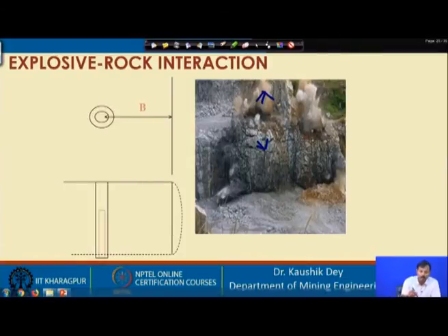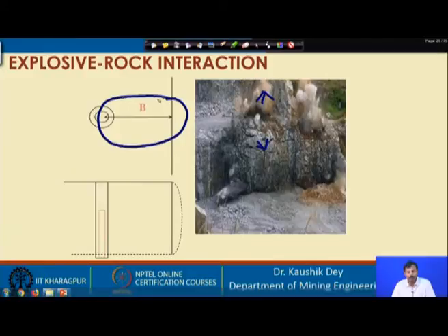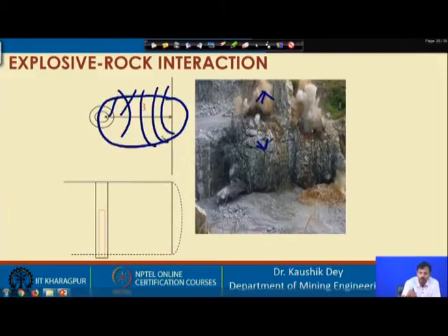So, our objective is to choose a burden such that the crushing zone, radial cracking zone and tensile slabbing zone are completed ahead of the gas reaching this position.